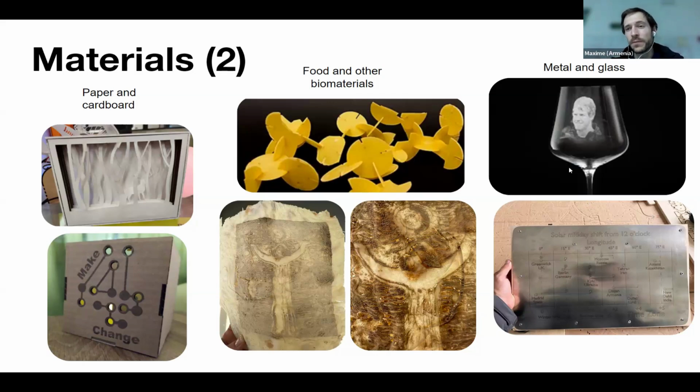With a CO2 laser, the one that you probably have, you can engrave glass. And with some other kind of laser, you can engrave metal. We did an astronomy project, but you need a shorter wavelength rather than CO2, which emits infrared light. If you have a diode laser, which emits visible light, it's possible to engrave metal.